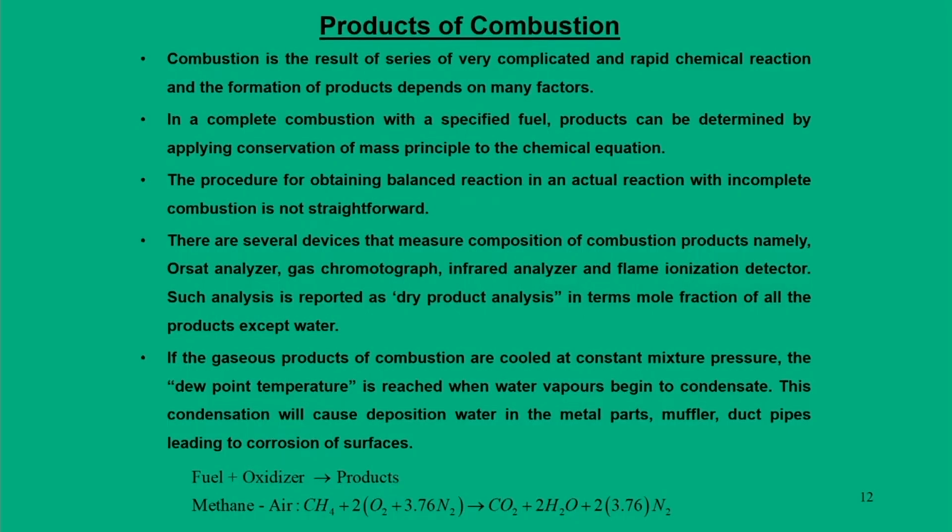Now, to quantify such parameters, there are several devices that measure the composition of combustion products, namely Orsat analyzer, gas chromatograph, infrared analyzer, flame ionization detectors, and all these are reported as dry product analysis, represented in terms of mole fraction.